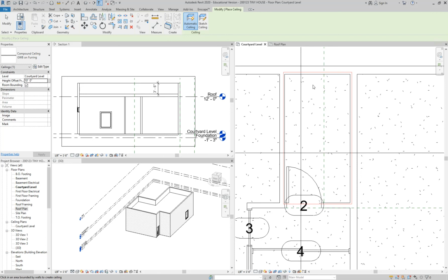Ashley? So when I go to fit ceiling and then change the type or whatever. Well, first actually before I go change the type, it tells me, in order to edit the sketch, please open one of the following views. Do you see how I'm in a floor plan? You have to put in your ceiling in a floor plan. So this section was just there for us. So here's why we have the section open.